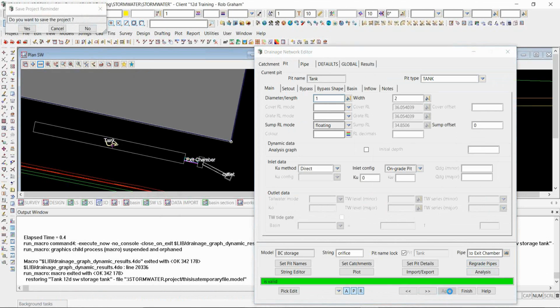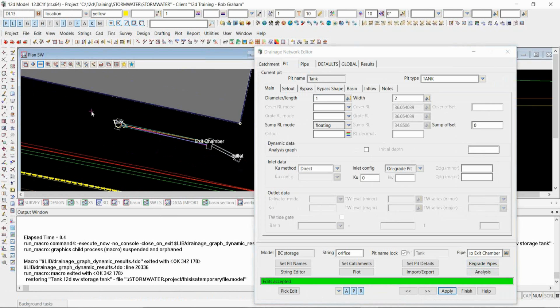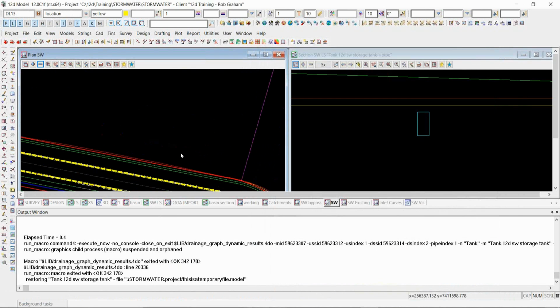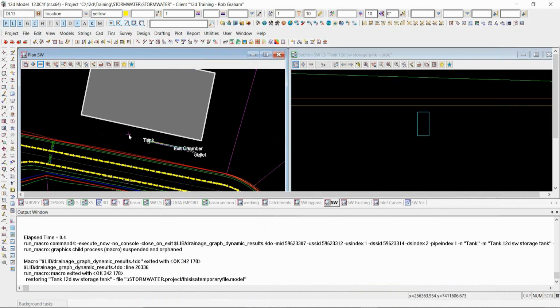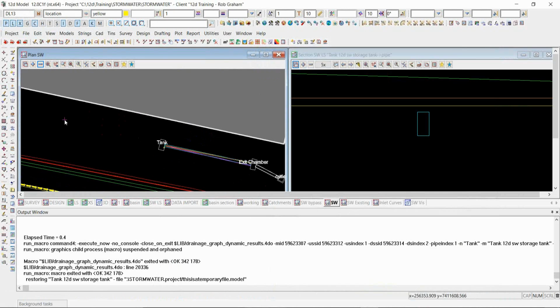That brings us back down to the very small tank. When we move our tanks, it's a really good idea to move the tanks before we resize them. So I'm just going to skip over one extra spot for a moment. I'm going to leave these nice and long, and I'm also getting a little concerned about the time. So I'm just going to add my box culvert straight onto the end of these relatively long conduits right now.